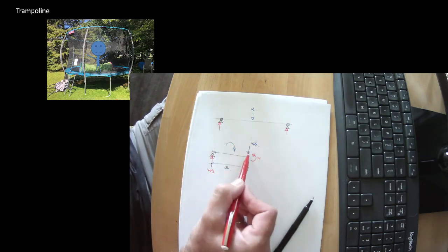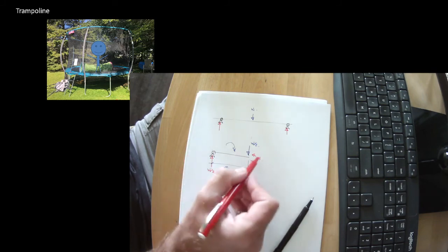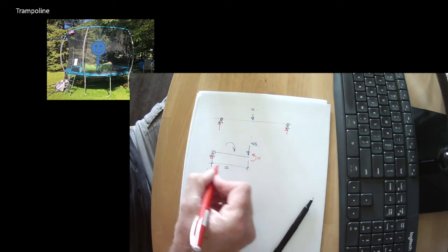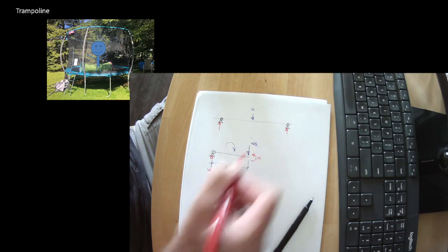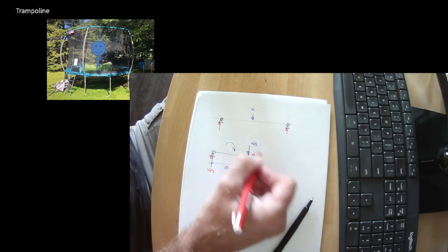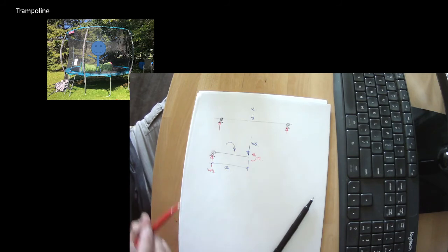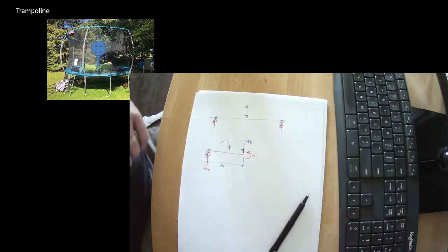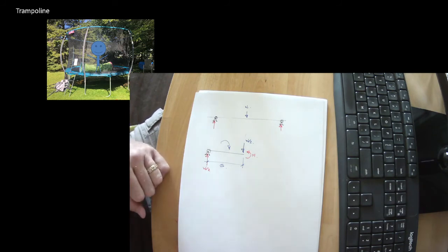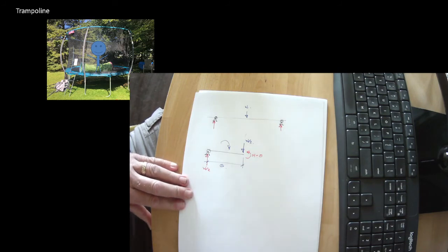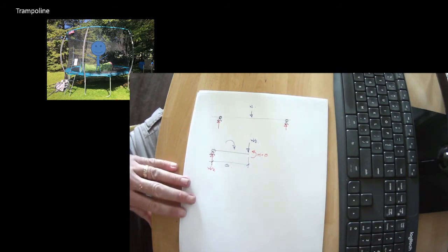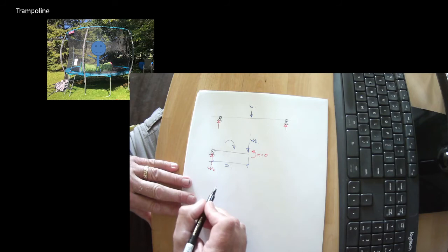We got our vertical components taken care of. There are no horizontal components, and we have bending moment. So the tendency to rotate this way due to the external applied loads are balanced by a bending moment in the other direction, and that's in equilibrium. That's our method of sections for a beam. What happens with a trampoline when moment equals 0? We are not in equilibrium. And this is what we call a shape active structure. Basically, it relies on changing shape in order to be in equilibrium.